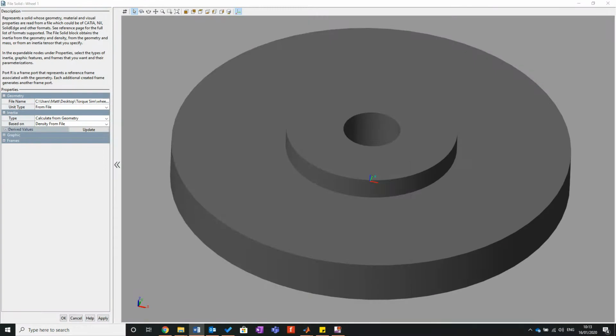So what I'm going to do is come back into here, go into my derived values, and it says here density from file. Interestingly, some CAD systems will allow you to export the density and actually put it in the STEP file. I've been going through SolidWorks this morning looking to see if this is a configurational option. Turns out it only is a function in Premium, not in the student version. So we still have to do this by hand. I say by hand, it's simply a value.